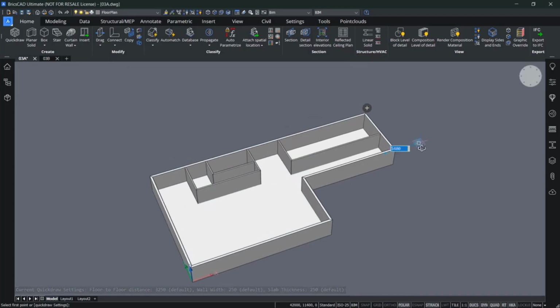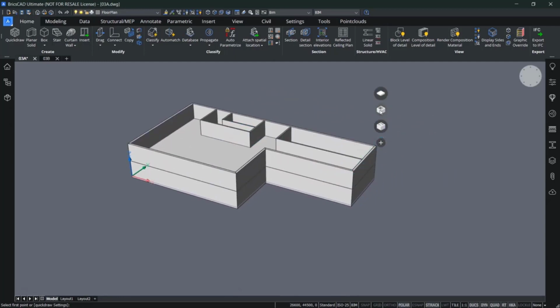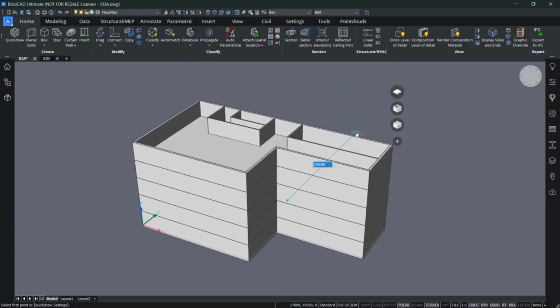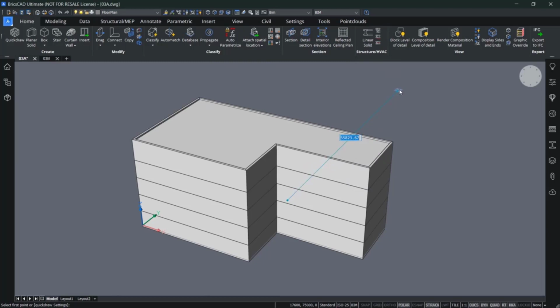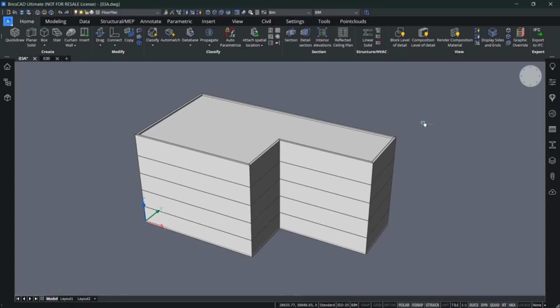Following along, here I can click on the plus sign to copy the entire floor, or just outer walls, or create a flat roof. So let me just add in some more floors. So I just click the button 4 times, so I have in total 5 floors, and then I can create the rooftop or flat roof. Like this, I can press enter or press escape to finish the QuickDraw command.